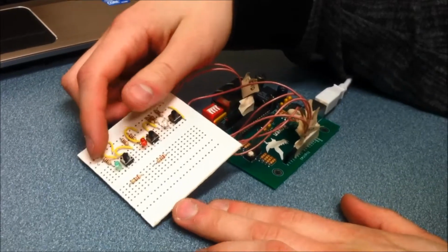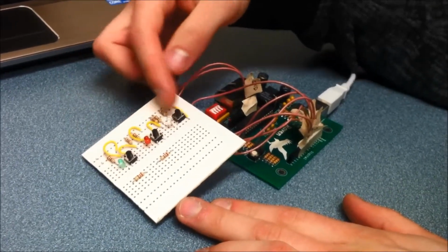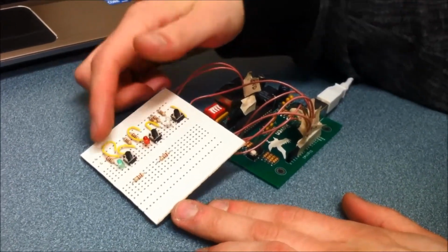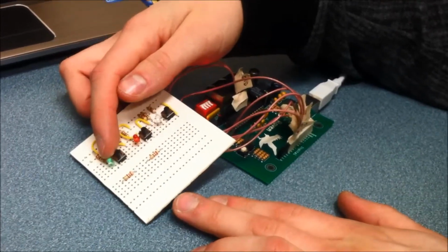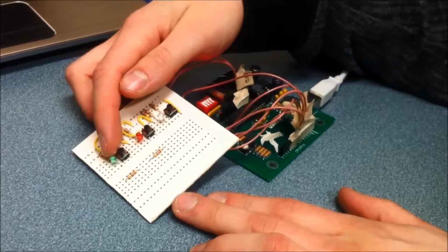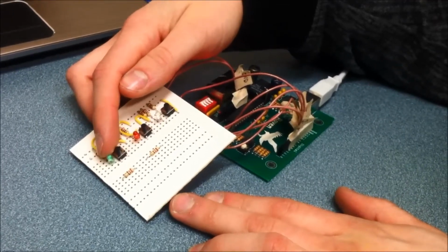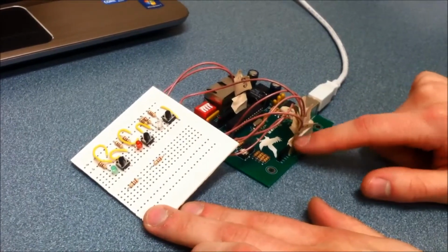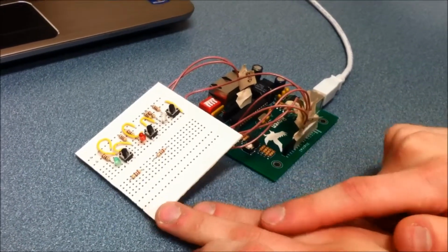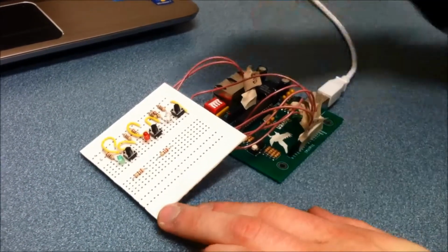On our board we have 2 leads going to both power and ground. These power and ground feed into our 3 LEDs and our 3 buttons. Each LED has a resistor before the LED, which uses up the volts so that the LED receives the required 2 volts. After each LED is a lead that goes back to the Raven. A low value to the lead turns the light on.